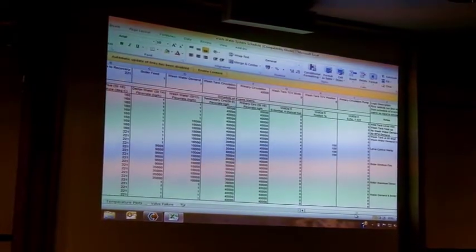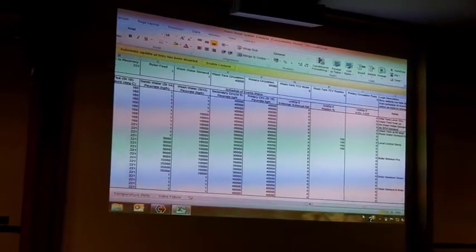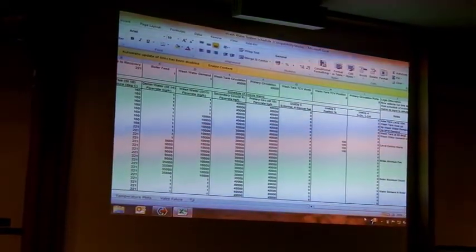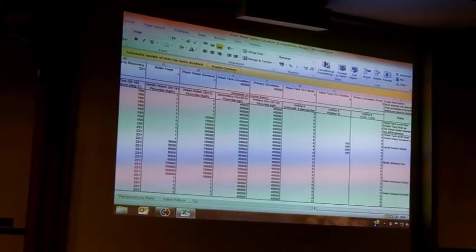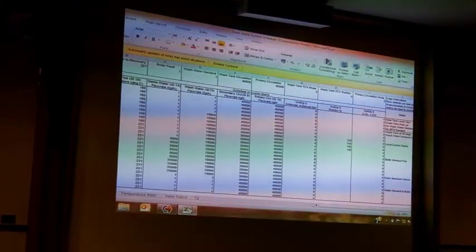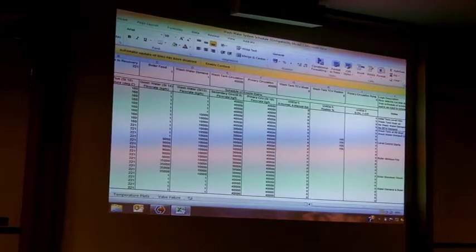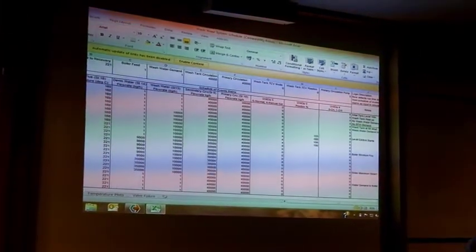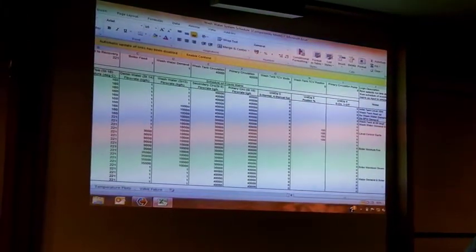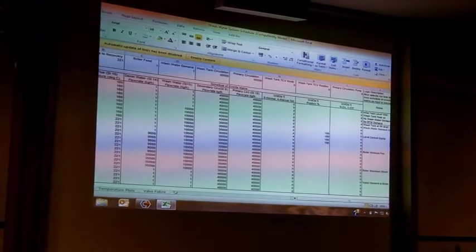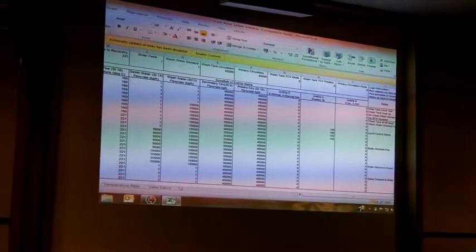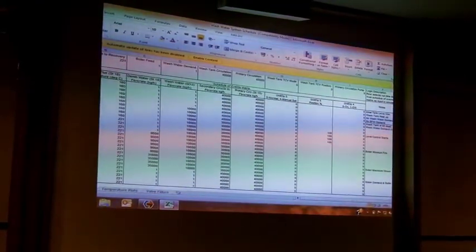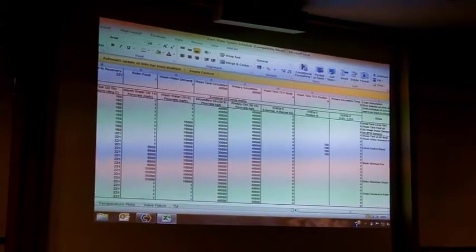So there's the matrix that's going to control things, and I hope you can see the potential benefit in a HAZOP situation where you've been challenged with various things. You could actually set this matrix up to really respond to challenges that are coming out of HAZOP.